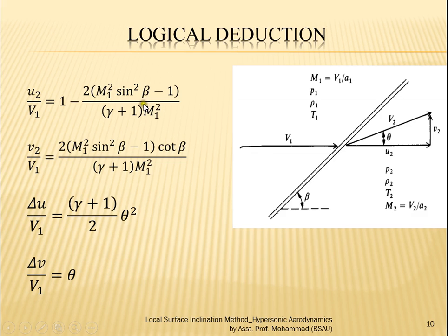Theta is just theta here. Sin theta becomes theta and all those things, and theta comes through the theta-beta relations, again in the case of hypersonic assumptions. We have already seen in the hypersonic assumption that for gamma equal to 1.2, the theta-beta relation becomes beta equal to 1.2 times theta. The same relation: theta is equal to gamma plus 1 by 2 into beta. So just replace beta by theta, and these things will come into the picture.